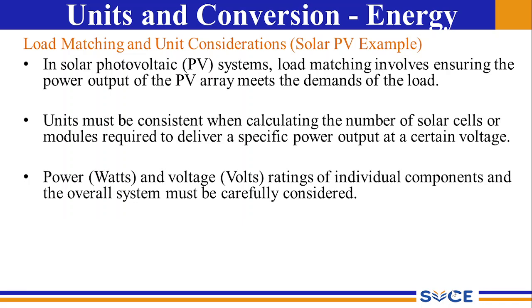A photovoltaic system involves the use of multiple PV arrays, basically photovoltaic panels. Each panel will be rated at a particular voltage and can withstand a certain amount of load. When you want a higher voltage system, let's say each PV array can give 4 volt, but your requirement is 20 volt, you can have 5 arrays in series.